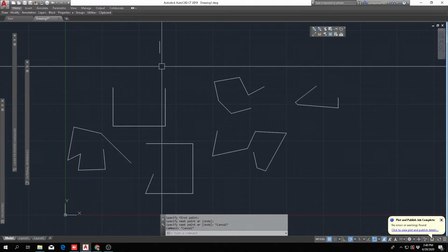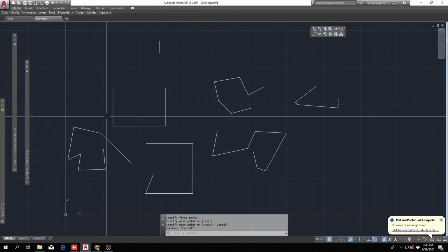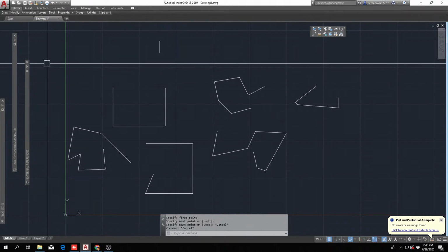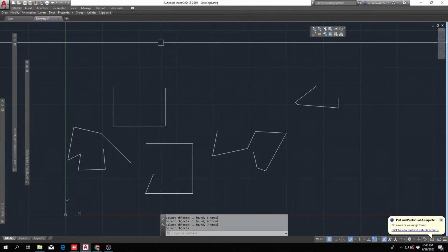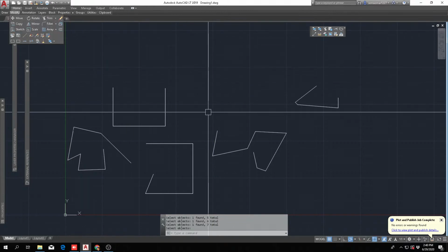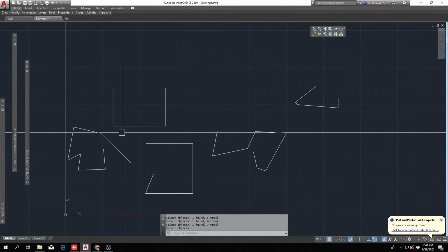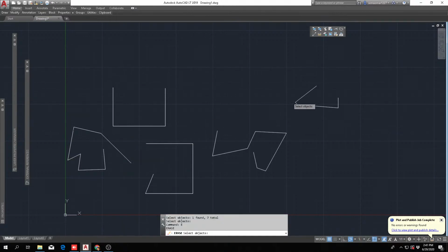lesson today. So another tool that I want you to learn once you already drew whatever lines you had in there is, go back to, now let's use the modify command or pull down menu, modify. And then as you can see here, you have your erase. You're gonna click on that, erase, and then you're gonna click on whatever lines you wanna erase. It's just letting you know what the erase command is. What's the shortcut for that? It's E, spacebar, which is enter, and it's the same thing.